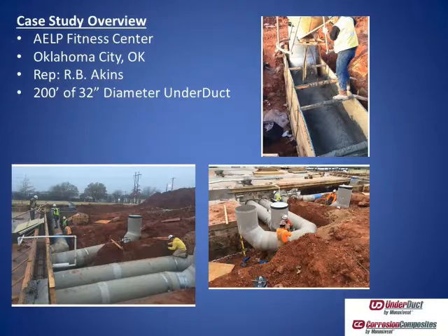There's a hold down method, and we gave them some instructions, and you can see some stainless bands around those ducts. If you look at the photo on the lower left where the man in the yellow shirt is, right below him is a stainless band. That's the only time when it would float out, is when you're trying to encase it in concrete. When you're putting it down in dirt, you don't have to have any hold downs.